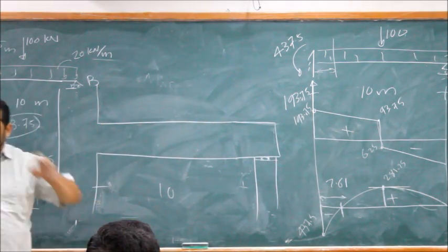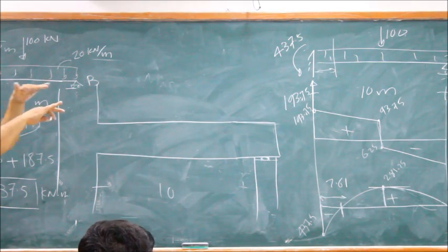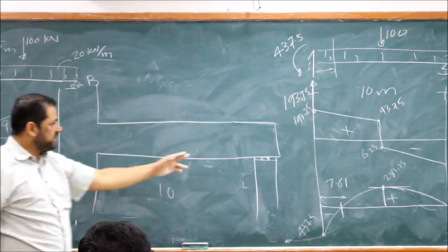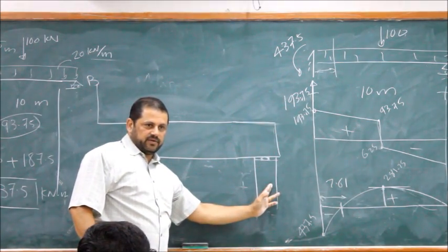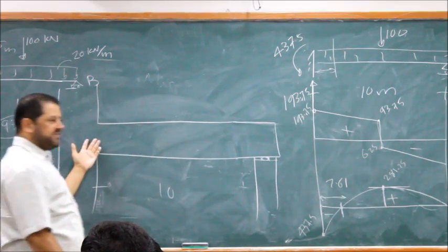Look at the bridges, you will see that the beams are sitting on the piers, the walls. They are sitting on them, which means the beam is free to move in this direction but cannot go down. So this is a roller, just the beam sitting, and this is fixed here.